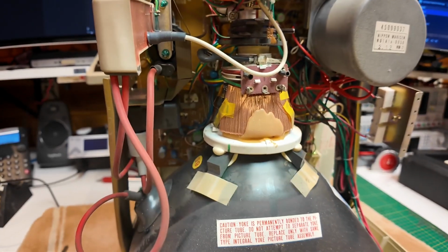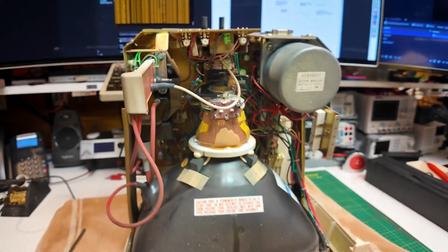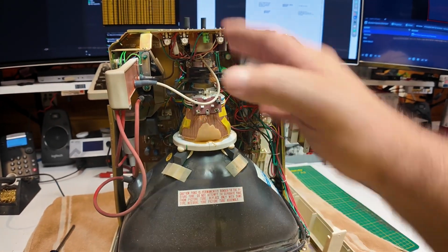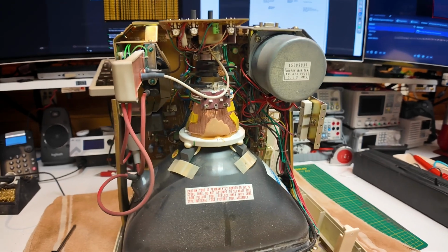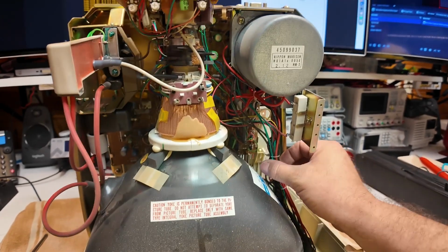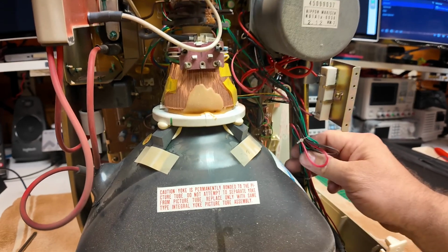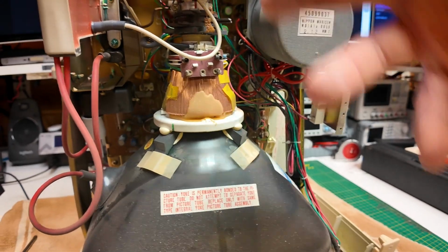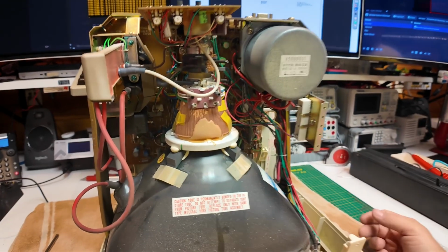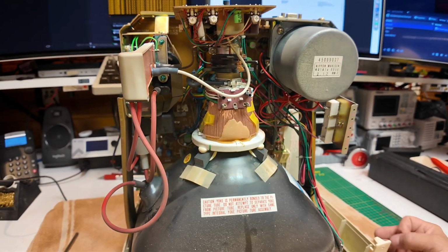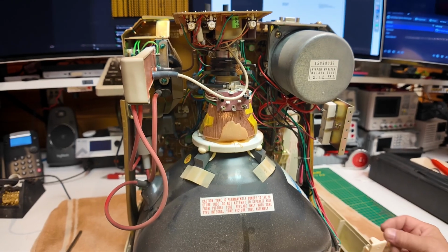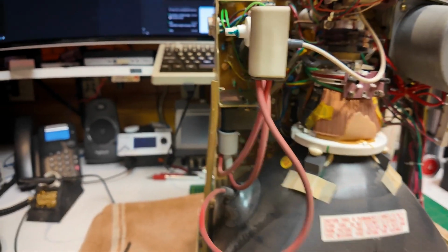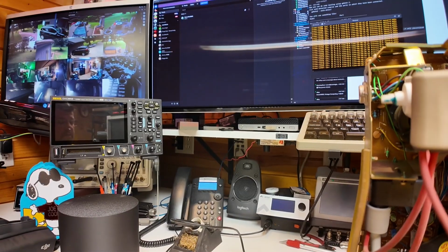And probably the most difficult thing here is going to be figuring out how to work on this thing, because I don't know if you can tell, but the board is underneath of all of this stuff. So hopefully there's... and if you look at these, sometimes there's wires wadded up like this with a little tie around them, and the reason for that is so that you can loosen things up and get the board slid out, like this, in order to get to where you can work on things. So see if we can't try and figure out where the B plus voltage on the rectifier circuit is supposed to be, and then maybe get this guy fixed.